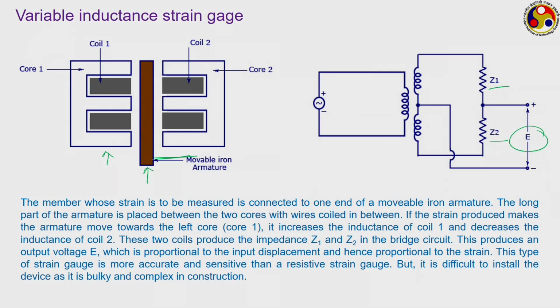are used more for measurement of a secondary parameter, that is, instead of strain we are measuring strain, but our final objective is not to measure strain, rather something like, say, pressure or flow. In those kinds of situations, generally we go for inductance and capacitance based instruments. So, if such a situation appears when we talk about those parameters, we may be discussing a bit more about inductance or other kinds of strain gauges,